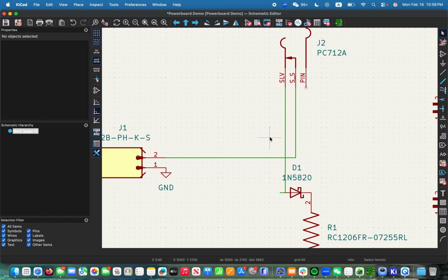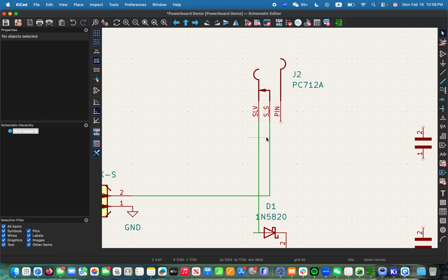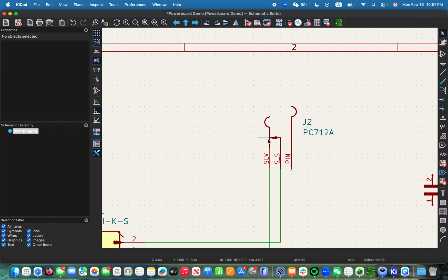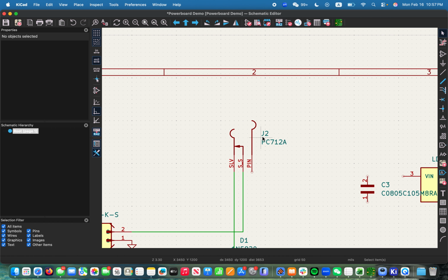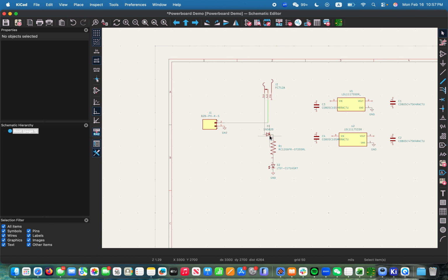Now, realistically, this thing is basically a connector. So the battery current, the battery power goes through this line and goes through this line. Now, here is a physical device that you will see on your power boards. Once you unplug it, then the current flows through this arrow. If you plug it back in, there's no connection between the middle pin here and the left pin here. So that's how that physical device works. So we don't want these two pins shorted down here because then it's pointless having a switch on this end.